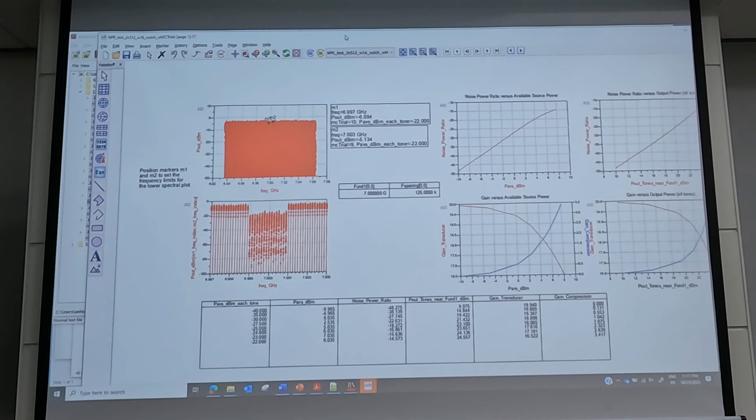Because if the amplifier has a good IMD, with a different load pull, maybe not just peak power, maybe low IMD, then it will give a good NPR. Is it true? Probably. I've never investigated the link, the correlation, but it seems likely. Not a single tone, only the signal applied, like maybe ACPR, it seems.